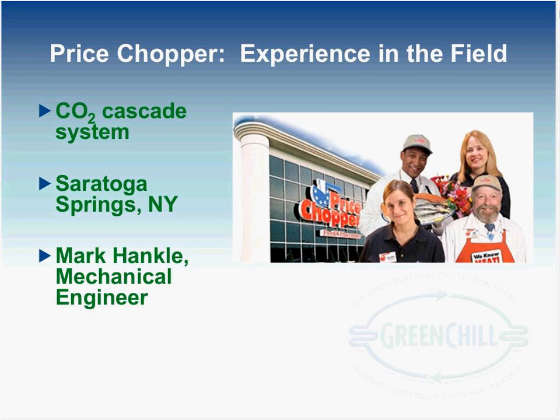The second question I had was, I didn't hear anyone mention any issues at all with oil management on the CO2 DX side, the low side of that Cascade system. Any problems with oil management? This is Mark. We haven't had any issues with the oil. The only one thing that we came up with initially, and our tech could come up with, is a way to add the oil to the system with the higher pressures.